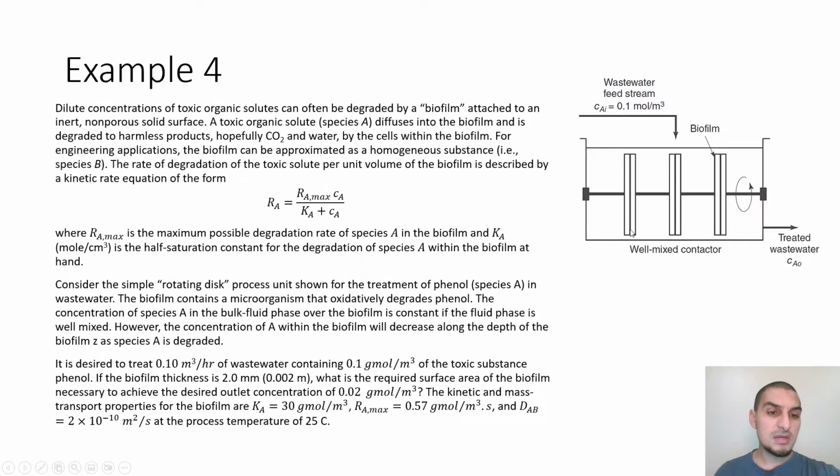And these discs that we mentioned are rotating discs, as it's mentioned here. They rotate to agitate and make sure that the tank is well mixed. This is a very important point that we will discuss later: why it's important to keep in mind that this is a well mixed contactor. So this shaft is rotating, exactly like car wheels are rotating. You have a motion at the beginning of the shaft, which transfers the motion to all the discs here. And by this we can tell that the concentration anywhere in this tank is the same. So this is the main part of it.